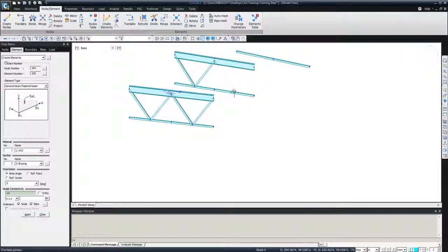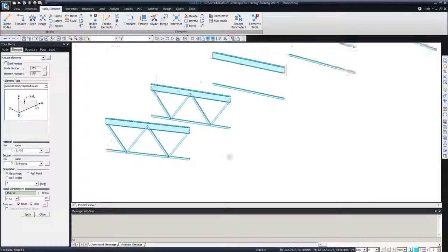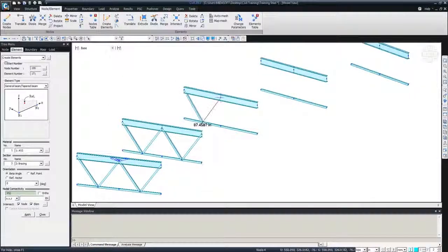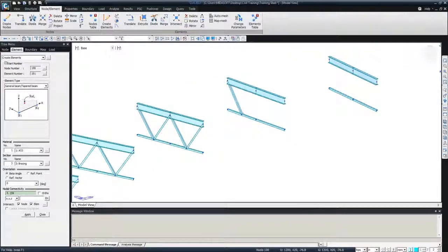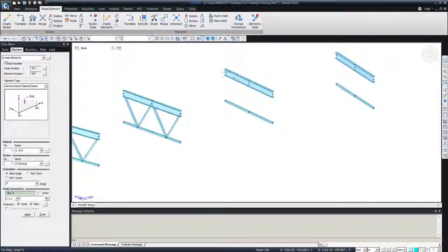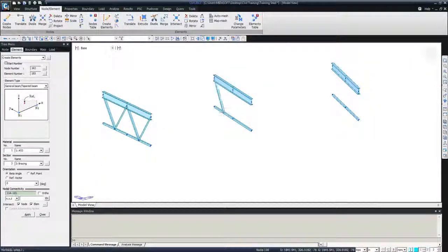Just know that what we did was create these additional nodes down here and down here, but these are not connected to the top of the girder, because we are supposed to make the girder and these cross frames work together as one system. To fix that, to ensure that they are connected as they are supposed to be, we're going to use the elastic links of the rigid type to make that connection. So that's a very simple step.